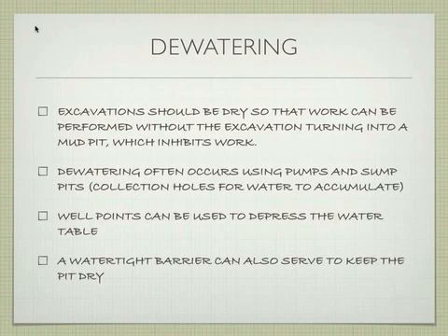Okay, so the problem with pumps, does anybody have a sump pit at their house? Okay, I do. It sometimes happens, it depends on how much water is around your house. What happens is you need a place to put the pump. If you're going to put a pump, you need a place where the water is going to collect, which you can put your pump in and then pump the water out. So they dig what's called a sump pit, which is just a simple hole in the ground that's lower than everything else, so water flows into that hole. You put your pump in that hole, and you pump the water out of that hole.